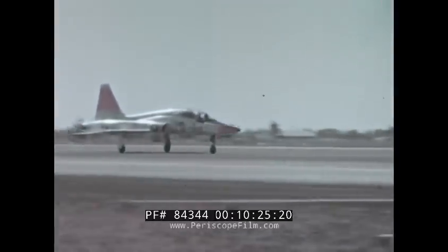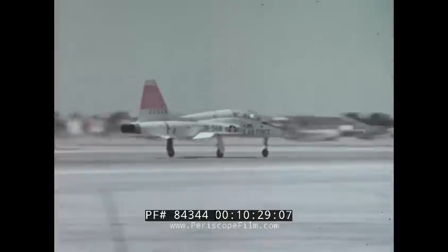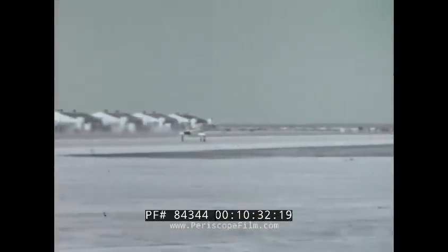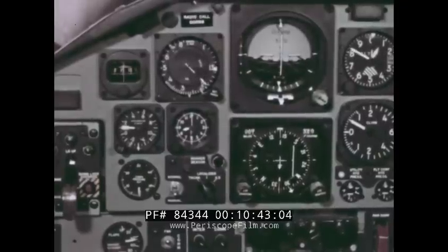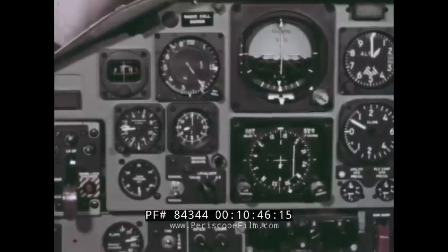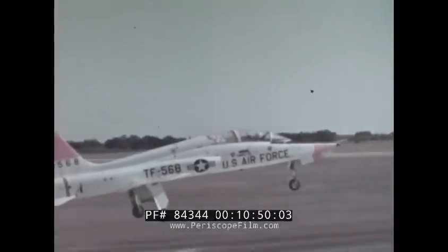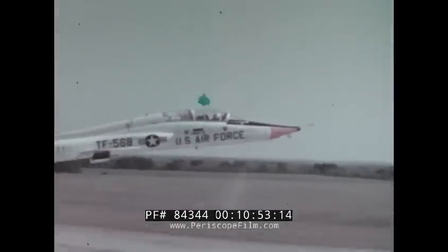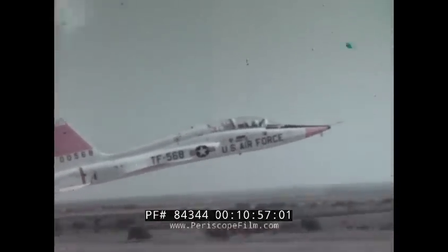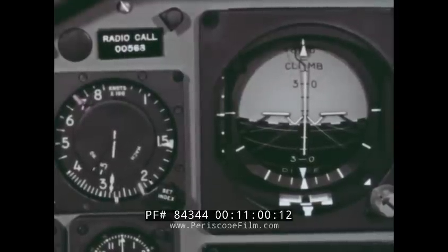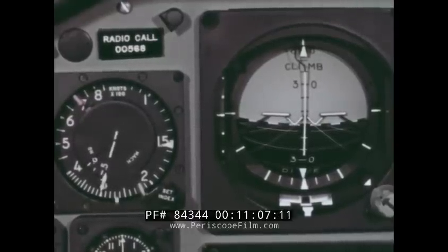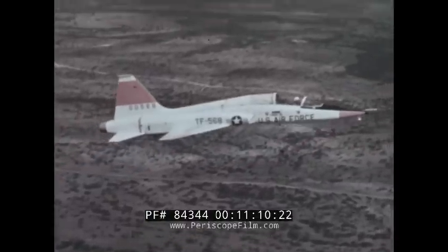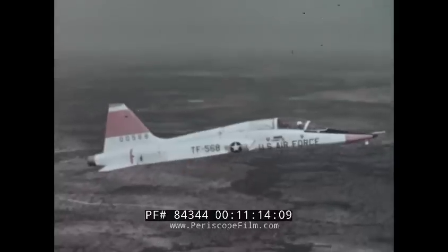Apply initial back pressure at 140 knots. Establish an 8-degree nose-high pitch attitude. You'll become airborne between 155 and 160 knots. When the instruments indicate a 500 foot per minute climb and airspeed is at 200 knots, retract the landing gear. Acceleration is so rapid that flaps can be retracted immediately. Maintain your 8-degree pitch attitude until airspeed approaches 300 knots, then reduce throttles to military. There will be little or no change in pitch attitude, since your climb angle will also be approximately 8 degrees.